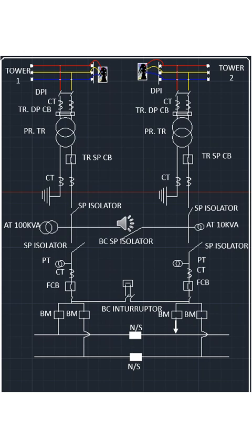Another system we also know is feed extension on the 25 kV side. Suppose both power supplies fail in the traction substation, then on the 25 kV or 2 into 25 kV side we can extend the feed from the other traction substation. So there are many options to keep the power supply uninterrupted.